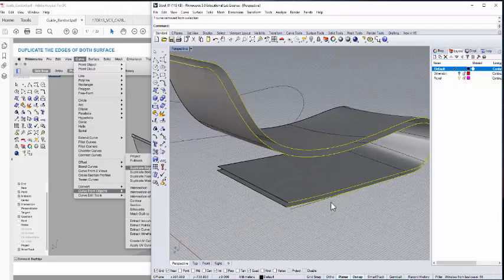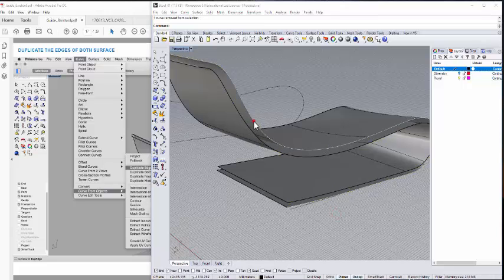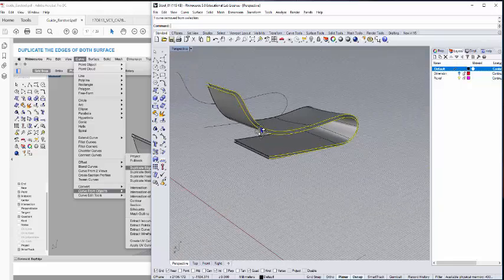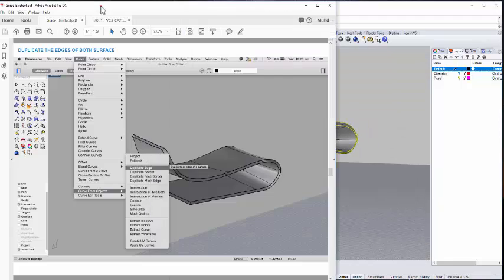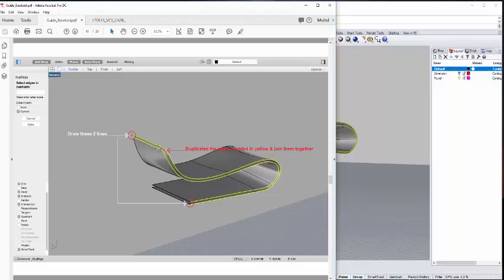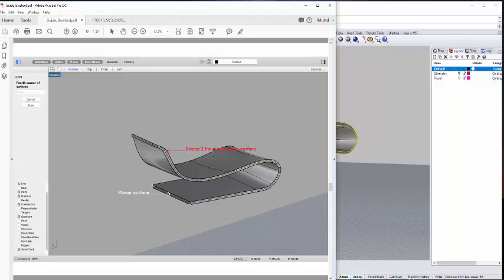Okay, just unselect. So right now let's just select the top, select the bottom, double check. Yep, it's okay. Draw the line, draw two lines here, and then you sweep two to close up the surface, and then planar surface down there.